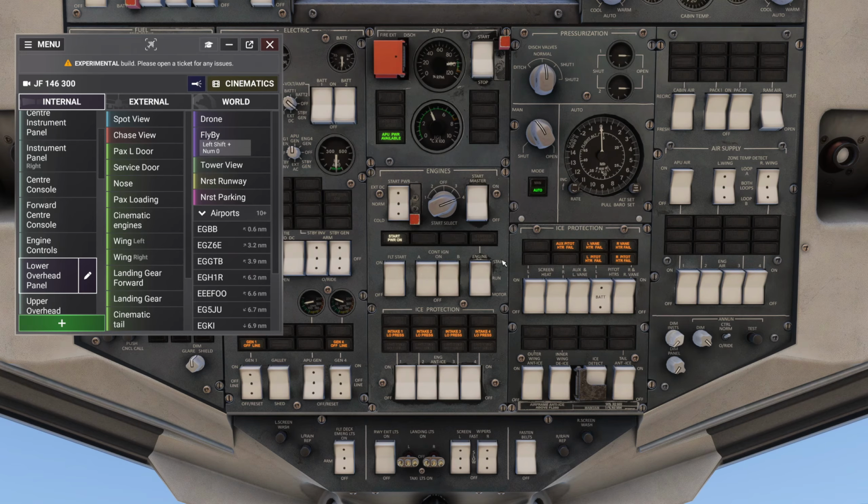Okay, and when do I set the fuel on? Which valve? Typically, you'll want to switch on the fuel flow just before you press the start button so that the engine gets the proper fuel supply as it spools up. Usually, you'll see the N2 rising and the EGT starting to increase. And then once you see that initial spool, the fuel flow should be engaged. Just keep an eye on those values and we'll make sure everything's in the correct range.